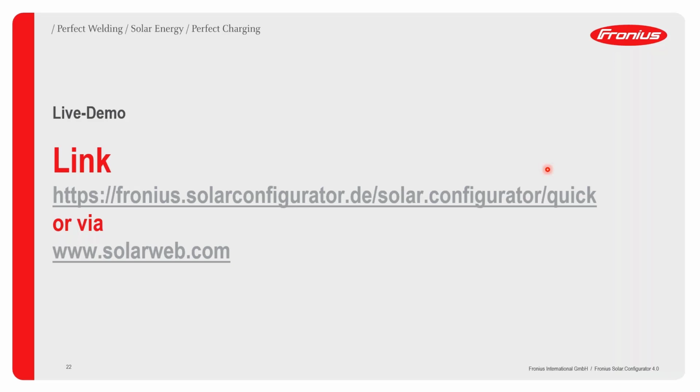Just remember, with Fronius solar inverters, we're actually very good in the fact that we can unbalance our trackers. So you do not have to have the same amount of modules on each tracker. You can have 80% of your modules on the first tracker and 20% on the second tracker. This makes our inverters extremely versatile because you can pretty much throw a Fronius inverter on a roof which has maybe an extremely weird shape, where 20% is facing one direction and 80% is facing another direction. And the inverter will work perfectly fine without any degradation due to unbalanced MPPT trackers.